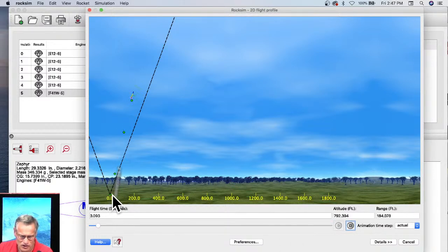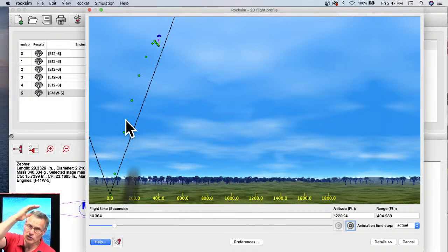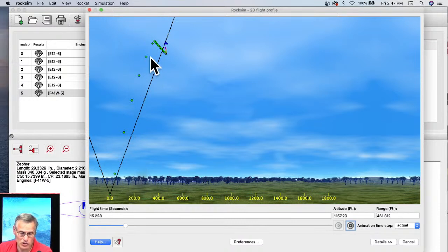You can see that we were angled, and then the rocket kind of wanted to arc into the wind, and that was actually pretty good because we want the apogee point, the highest point, to remain inside of this cone right here. If it had not wanted to weathercock into the wind, it probably would have gone out of the cone, and that would have been a bad flight.